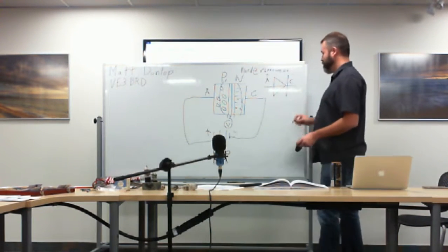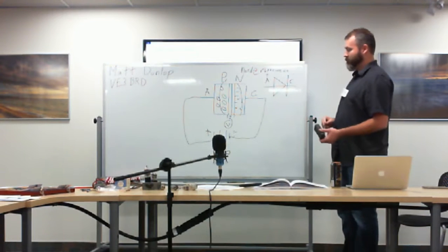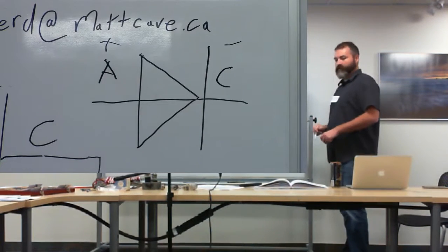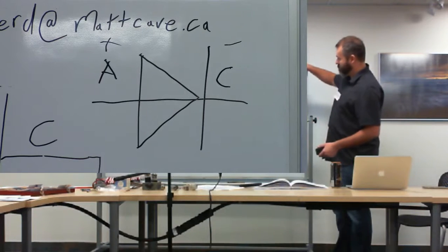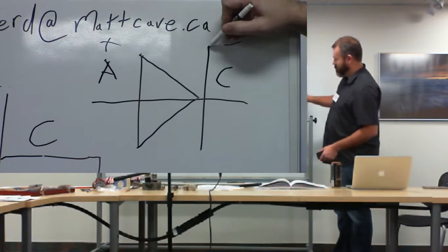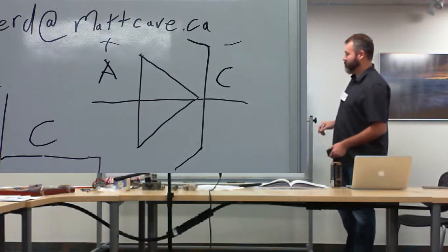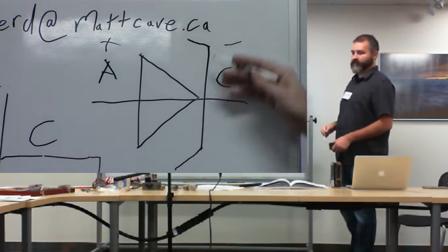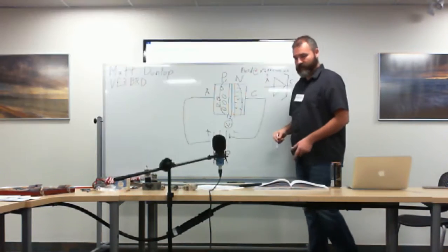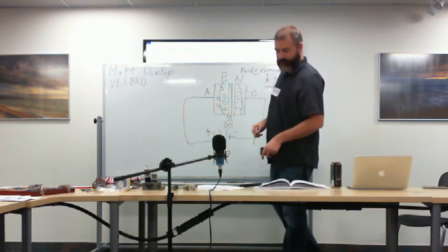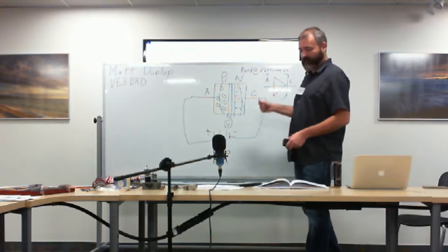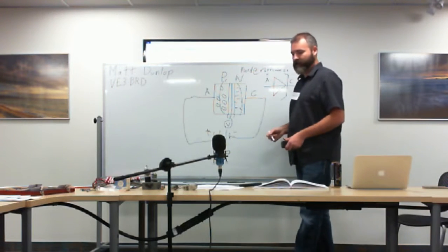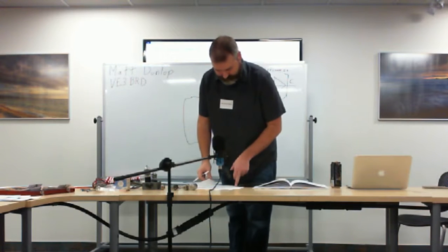There's the Zener diodes. Because they have the extra ability to be reverse biased so much that they will start flowing electricity, they have their own diagram. They have the little extra squiggly lines that denote a Zener diode. I didn't put that in there. I just realized I forgot that. But that's the symbol for a Zener diode. You don't need to know that for the test, but just FYI. You will need to know what a Zener diode is, though, and what it's used for.